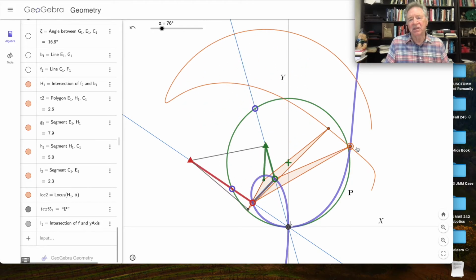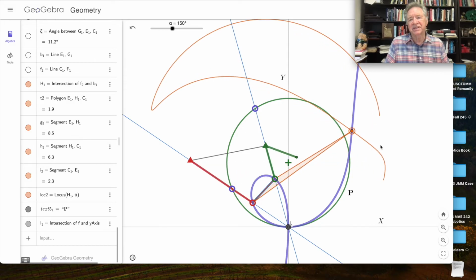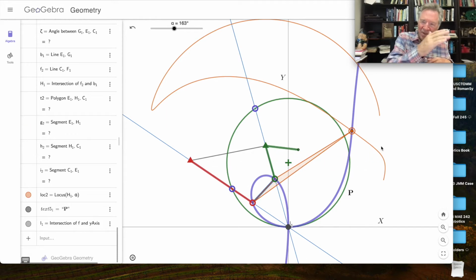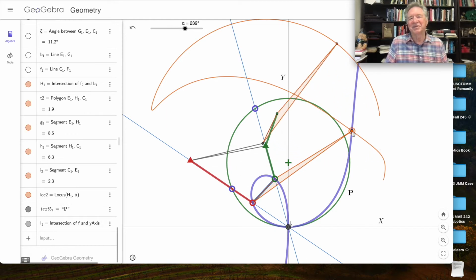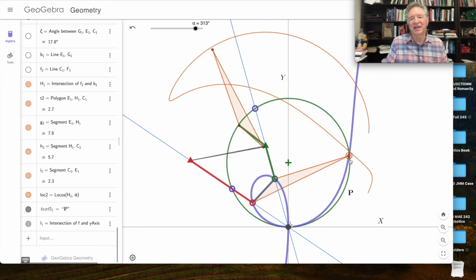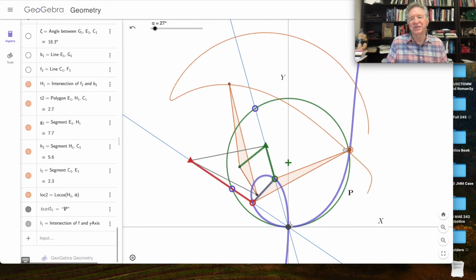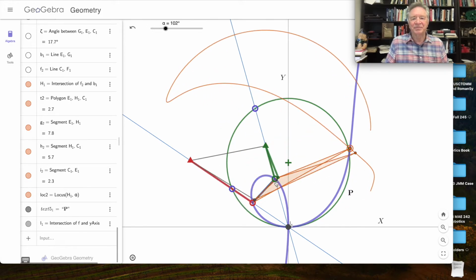You can actually be close to the inflection circle and still have a very large circle of curvature, very small curvature. We want the curvature to be near zero, so it's a straight line, but you can actually be close to it, and it's still fine.